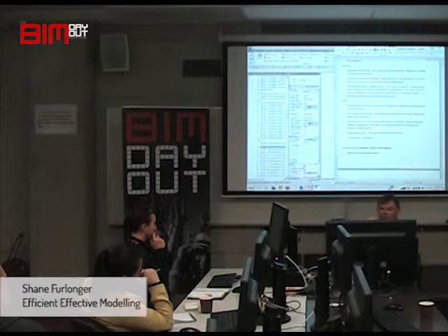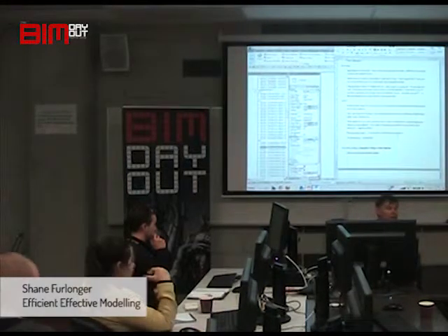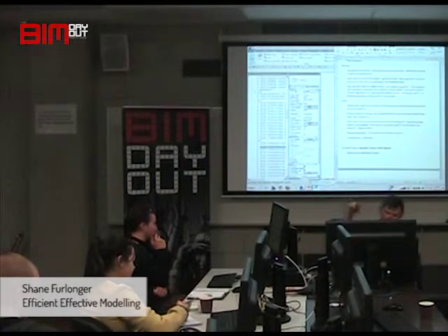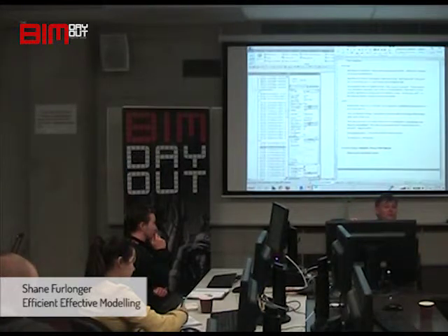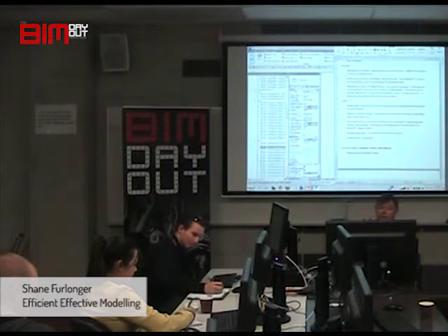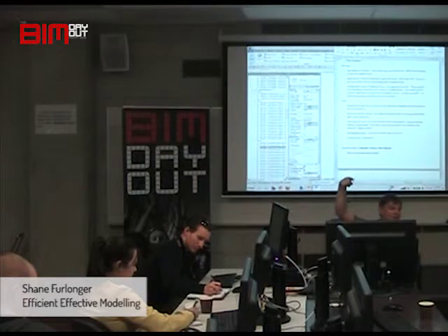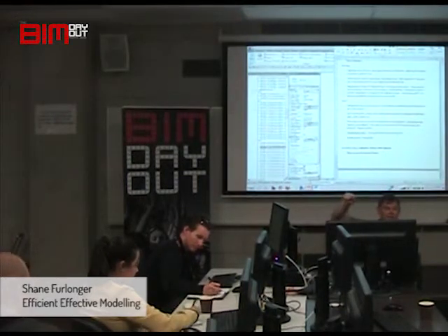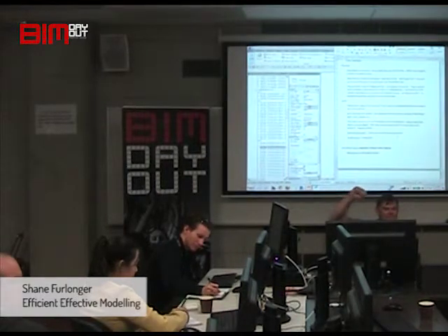When you're changing level heights, dimension them and say how high you want that level to be in the dimension. So you click on the dimension, activate your dimension, click on the level, sorry, activate your dimension and type in how high you want it to be, because that is in millimetres. And it doesn't matter how many times you change it up and down, it'll be correct. Because it looks really weird when you've got a floor-to-floor height of 3 metres, let's say, and your dimension says 2 metres 999. Same problems that exist in AutoCAD.